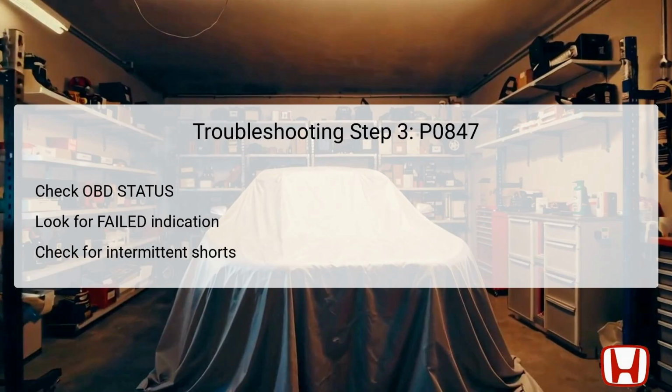If the HDS indicates a failed status, this suggests that there remains a fault in the system needing further investigation. In such cases, technicians should look for possible intermittent shorts that might exist in the wiring between the transmission fluid pressure switch B and the PCM, powertrain control module. This search involves inspecting the integrity of the wire harness and its connections to ensure they are secure and free